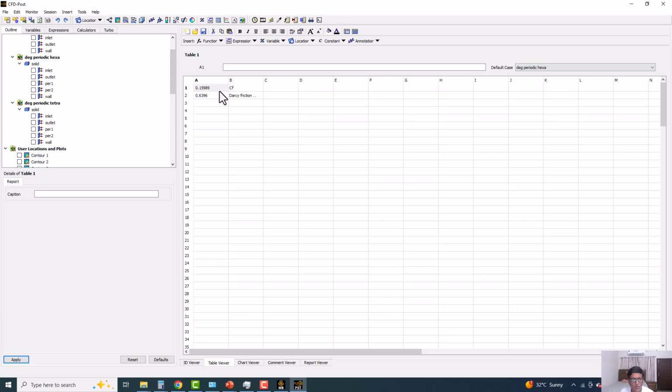It's almost the same if I use scientific digits to the second order accuracy. So they are exactly the same data. Only in the case of tetra meshing is the value slightly higher, but they are almost giving us the same results. So it means that the 30 degree sector, even with tetra meshing, although hexa meshing has a finer mesh, gives us the same results.